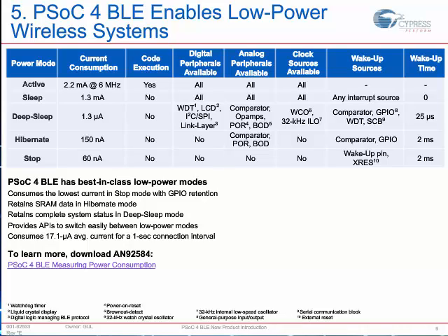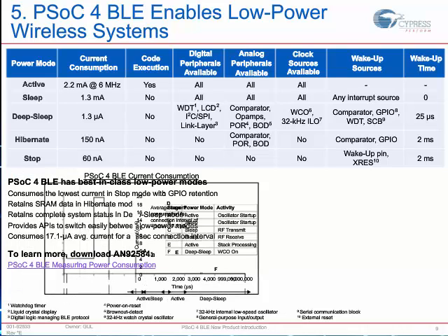This is where stop mode can be extremely useful. The system is essentially shut off, but its battery is plugged in, and it's ready to come back to life very quickly within 2 milliseconds, and it can stay on a battery for a really long time by consuming only 60 nanoamps. So I guess the lesson here, or what's interesting to note here, is